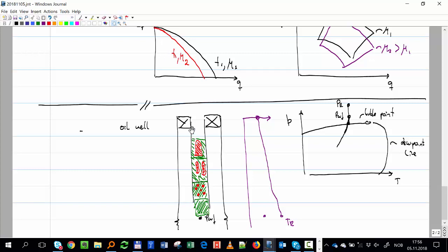And at the end, if the wellhead pressure is very low, that doesn't happen all the time, but here we reach wellhead pressure and wellhead temperature. If it is very low, the gas is going to be in a core in the center. All of these plugs, all of these flows, are going to form a channel with some liquid droplets, and the liquid will be just sticking to the wall. So all of that might happen in the wall.